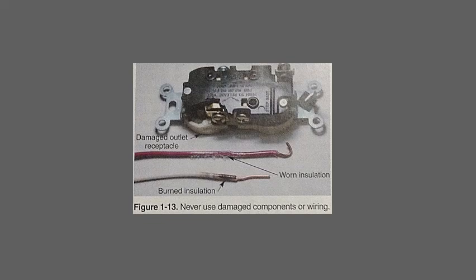Wet conditions. Often utility workers must repair power lines in the rain. Water is an excellent conductor of electricity, so special equipment and training are necessary to prepare them for these high-risk situations. Although you may not find yourself in a rainstorm, the rules of working in any wet conditions are the same. The first rule is to avoid it. If you're working on an entire house, work on the interior wiring on rainy days and install the service on a dry day.